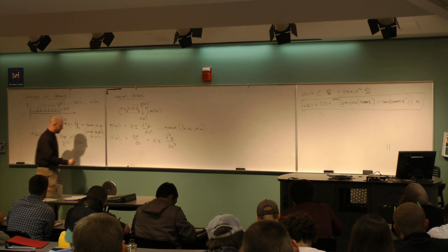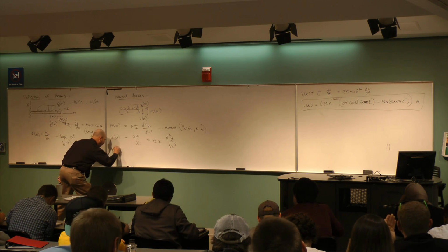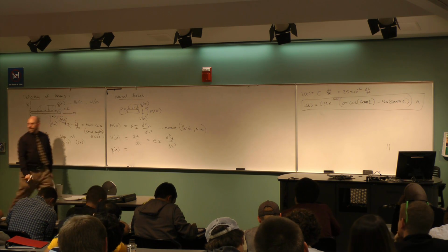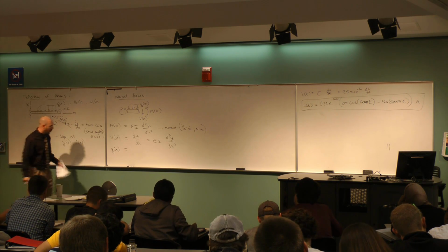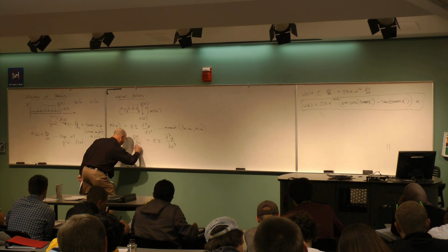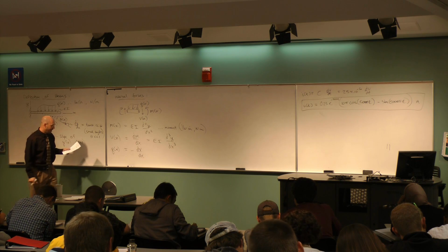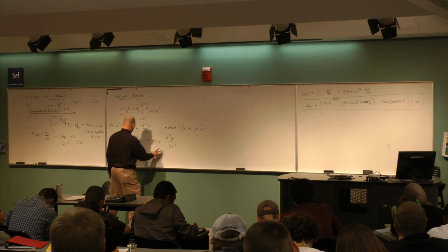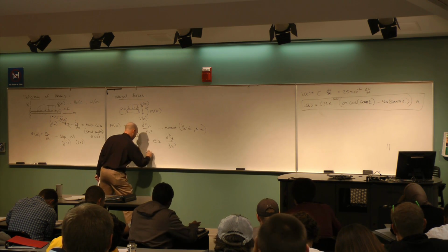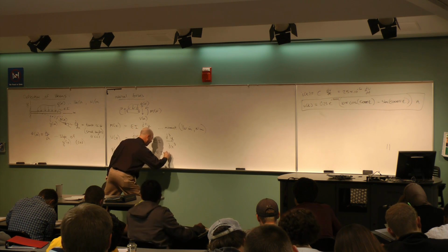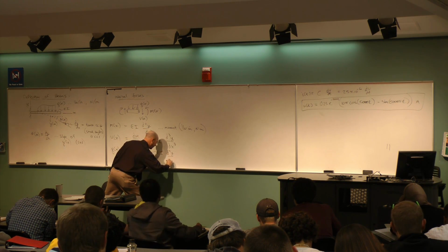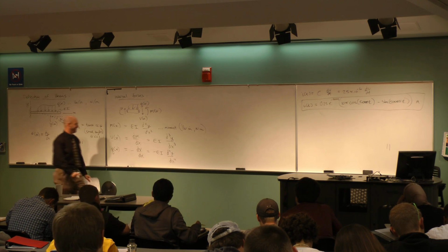And then finally, very interesting, these internal loads have to balance the external. And the way this works out is that the q turns out to be minus the derivative of the V, dV/dx. Okay, and so what I'm going to get here is minus the EI times one more derivative, 4 derivatives of y with respect to x.